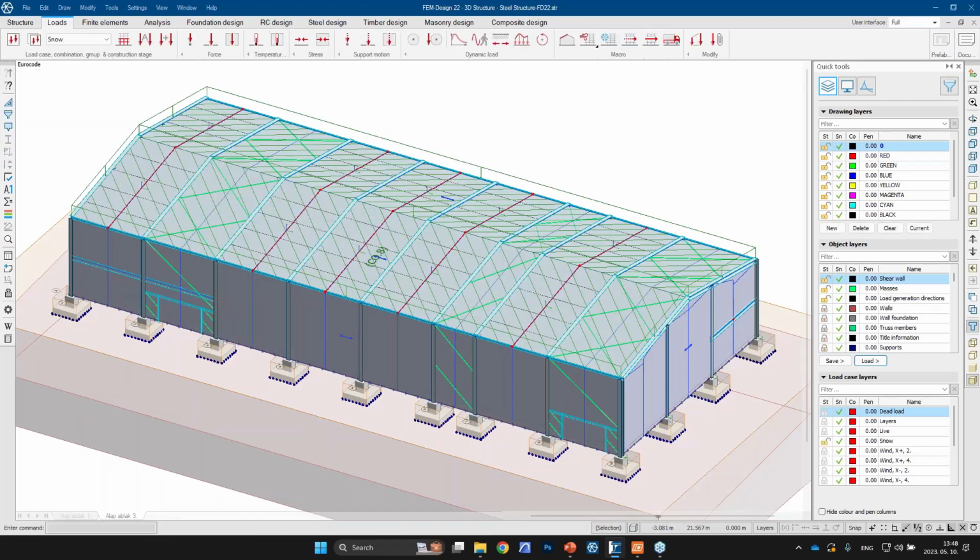Then I could go to the loads, and as you see, the client created different loads. The program automatically calculates the self-weight, of course. You can define a live load manually, for example, or you can create climate loads, such as snow load and wind components, based on wizards and using the coverings as climate panel objects.